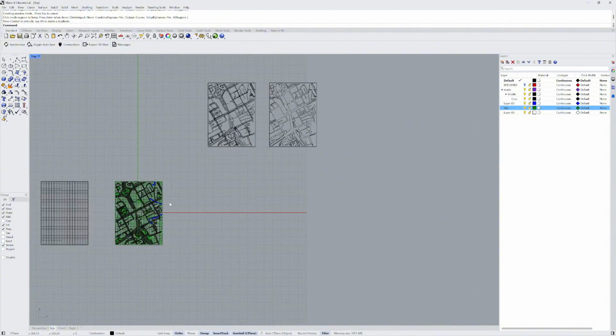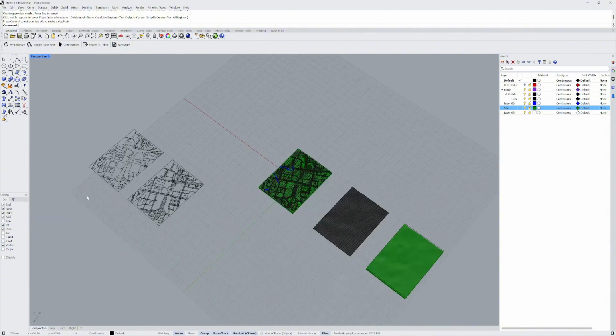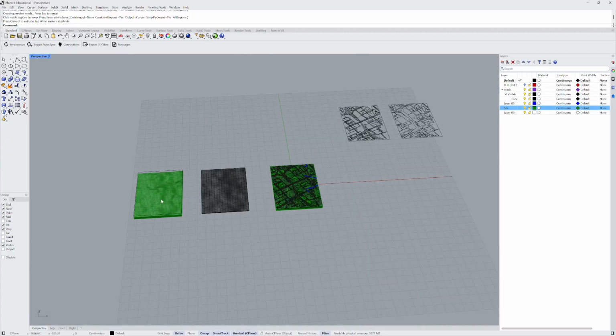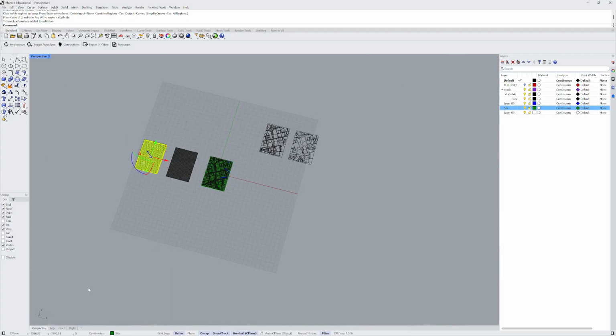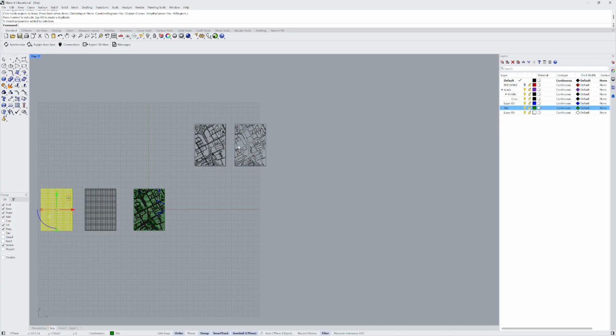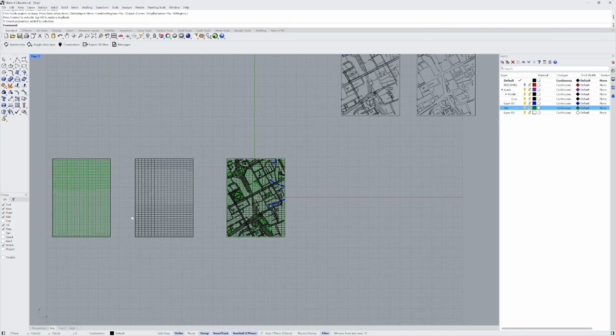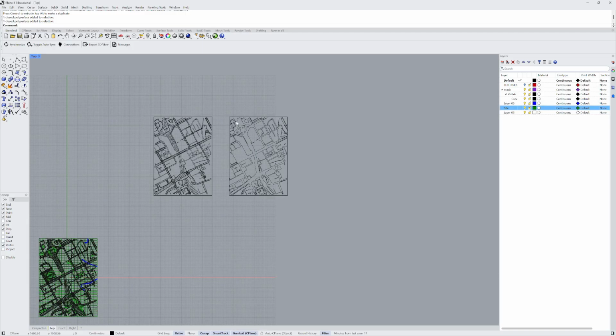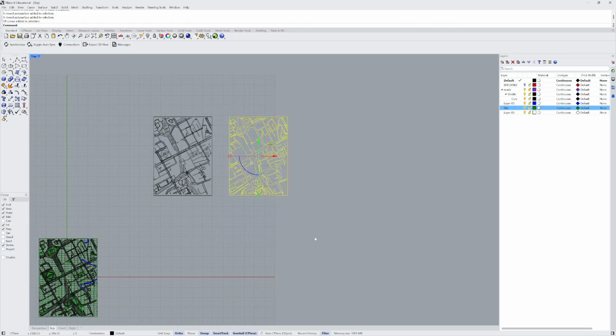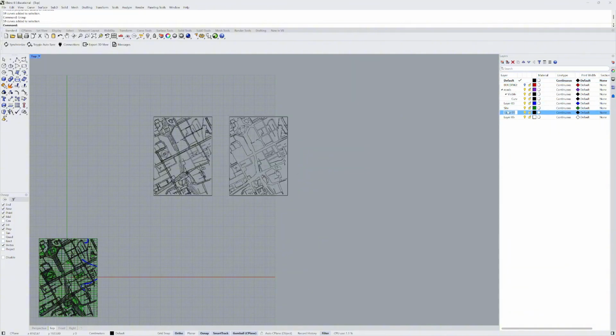Okay, so what I could do now is, I'm just going to demonstrate this to you just so you can see. If I take my site profile, it's going to go in the top view. So this is my site profile now. And I'm just going to take these curves that I created and group them together just so that they remain together. And I'm going to create a new layer where I'm going to say roads, curves, and they're my cleaned up road curves.